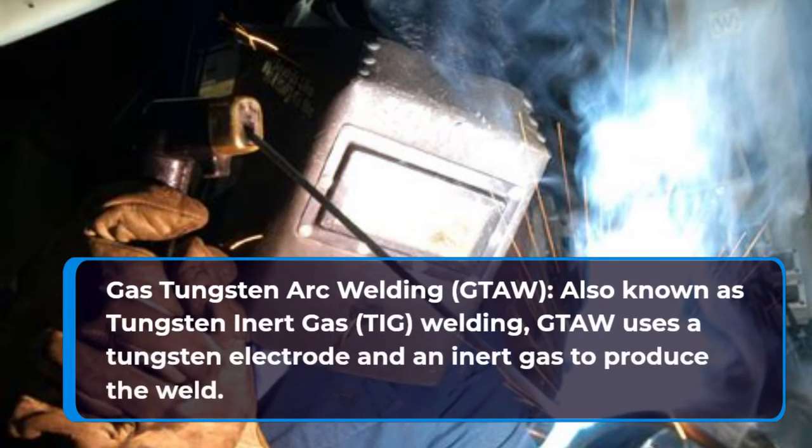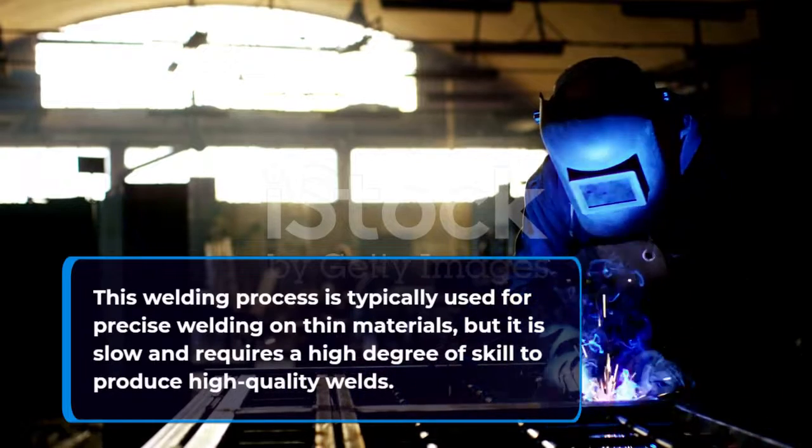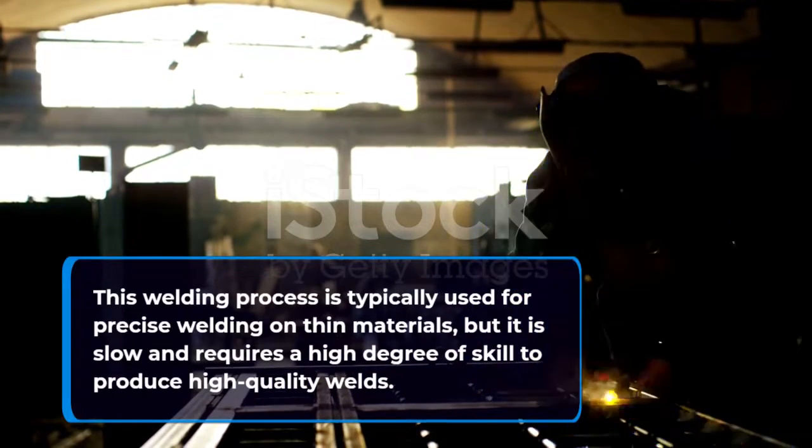Gas tungsten arc welding, GTAW, also known as tungsten inert gas, TIG, welding. GTAW uses a tungsten electrode and an inert gas to produce the weld. This welding process is typically used for precise welding on thin materials, but it is slow and requires a high degree of skill to produce high-quality welds.